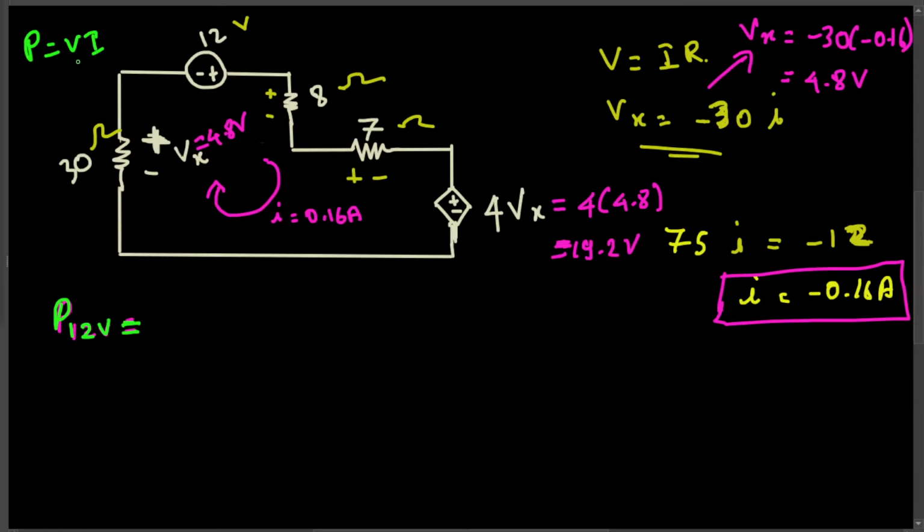I times R. So that's going to become I square R. Or you can apply Ohm's law in a different way, V is equal to IR, therefore I is equal to V divided by R. If you substitute I, that's going to give you V square over R. So P is equal to V square over R. So we have three equations for the power.